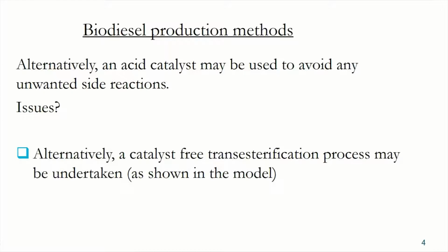Typically, under subcritical conditions, if you have an oil that contains water or has a high fatty acid content within it, you do not need an alkali or an acid catalyst. You just transesterify under high conditions of temperature and pressure. I discussed it at the beginning of the slide.